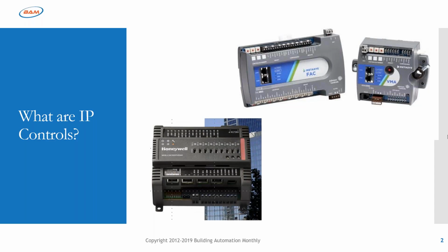There's like 60 plus BACnet object types. A device is a type of object, and the device instance number is a property of the device object type. So an object ID is going to be its ID, whereas the device instance number is going to be a property of the device object. Does that make sense?